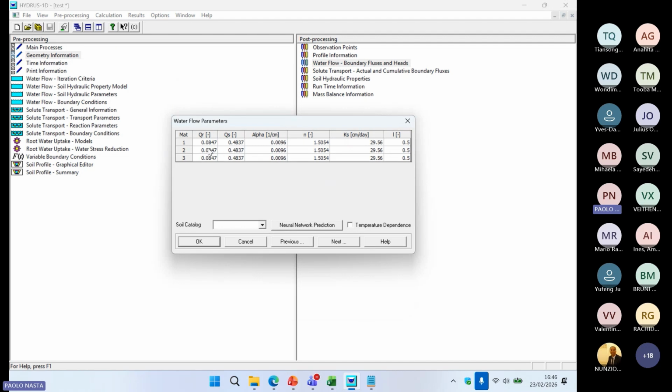Now we have to set up the Van Genuchten parameters for each horizon, for each layer. You see that in layer number 1, you have specific Van Genuchten properties. In layer number 2, we need to set the new properties. And of course, since we don't know anything about this mysterious soil profile, we're going to invent. And so in the second layer, we put a loamy soil. And in the third layer, we put a silty clay soil, okay? Just because there is no more time.